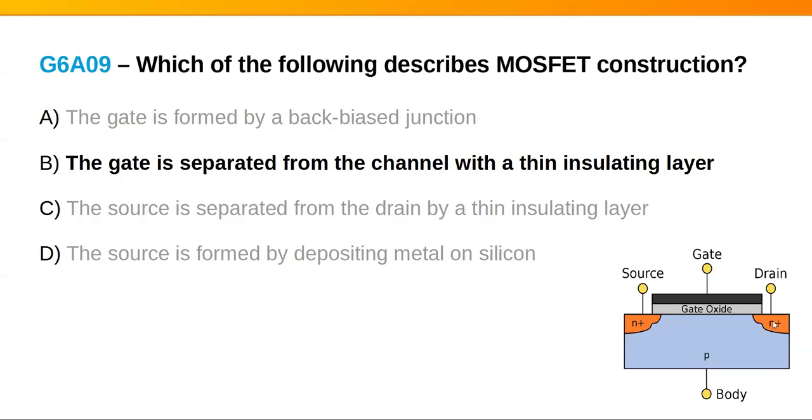Current flows from drain to source or source to drain, depending on your flavor, through the P material. So the P material has holes. The body's providing those extra electrons, so every time you fill in a hole, you create another hole and you get your quote current flow. What's the gate? How's the gate affecting that?